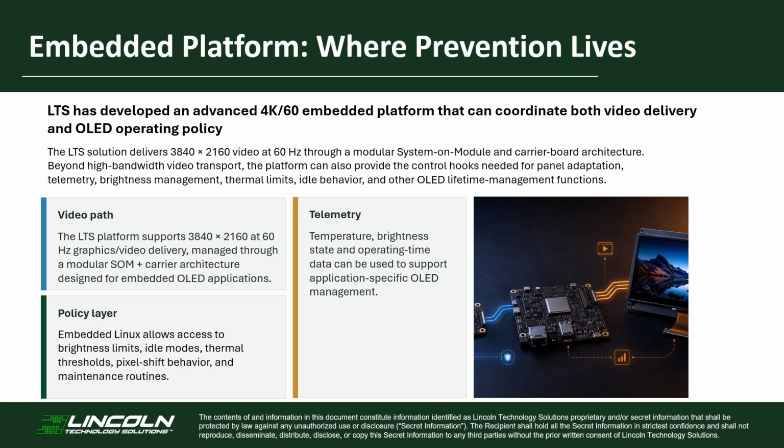Beyond the high bandwidth video path, embedded Linux can expose controls for brightness limits, idle modes, thermal thresholds, pixel shifting, and maintenance routines. The platform can also collect temperature, brightness state, operating time, and other telemetry that supports application-specific OLED policies. The important technical achievement is not only stable 4K video output, it's the ability to combine high-performance video transport and OLED-aware system control within the same embedded architecture.